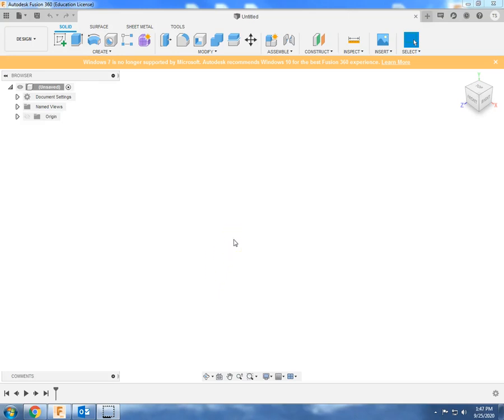Alright, so we're going to work on project 3 together here. One of the things some of y'all may or may not have seen in some of the earlier videos is how to change it to imperial instead of metric. You can go into, hold up, where is it at? Units. You can check this little box right here and switch it from metric, millimeter, to inch. So that's how you can change it. Personally, I like to work in inch, but you may or may not.